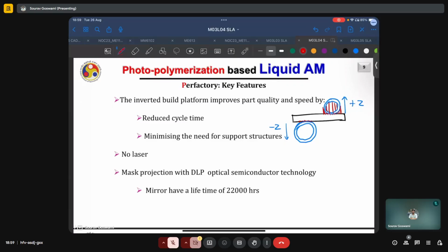We do not need any additional support structures because now the structure is entirely self-supported. Further, if any resin enters this hollow region, there is a very good chance that it will remain entrapped in building along the positive z direction compared to the negative z build, where any resin which might have entered this hollow region will automatically flow out under the action of gravity.